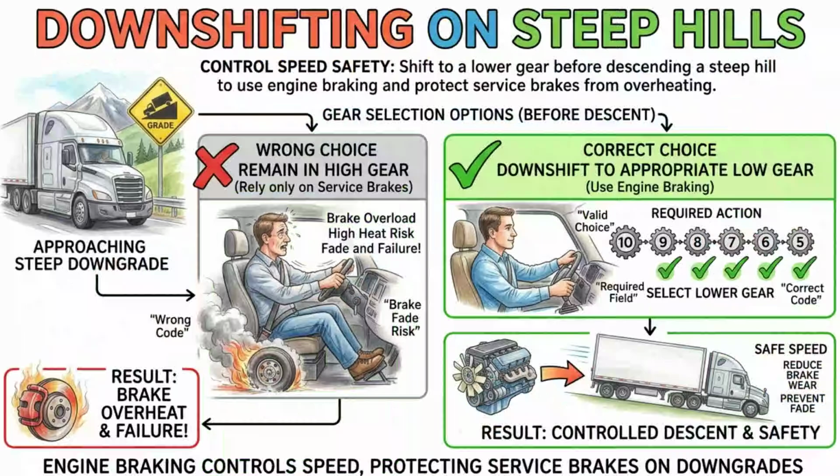Moving down to the steering system, examiners want to see that you understand how to spot dangerous mechanical wear. You must check the steering box to ensure it is securely mounted and not leaking any fluid. Then you will inspect the steering linkage, which includes the pitman arm, drag link, steering knuckles, and tie rods. None of these metal parts can be cracked, bent, or broken, and all castle nuts and cotter pins must be firmly in place. A failure in the steering system while driving a heavy commercial vehicle is catastrophic, which is why exam questions frequently focus on these exact components.